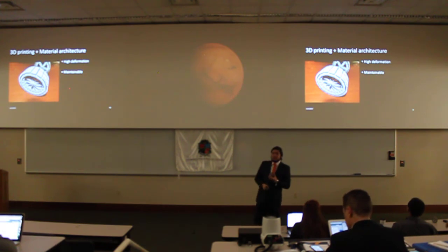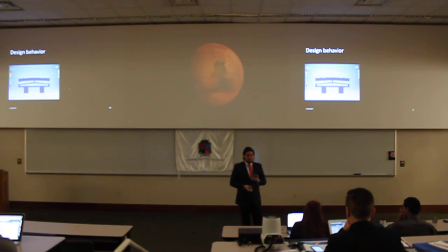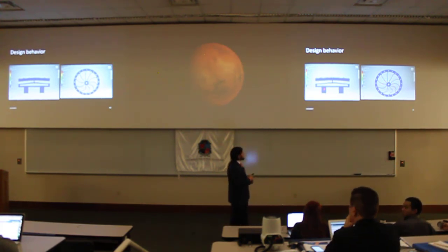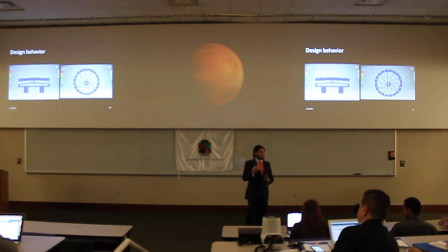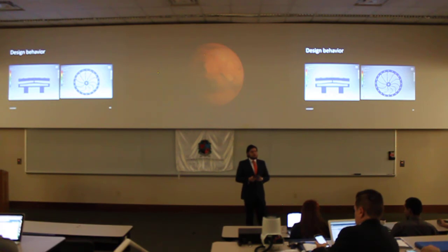This architecture allows for high deformation, and as you can see in this very basic finite element analysis, we have a high deformation, but the point here is that although it has high deformation, no point has a higher stress or a plastic deformation, so we can recover from this deformation. So the architecture plays a major role in this type of structure.